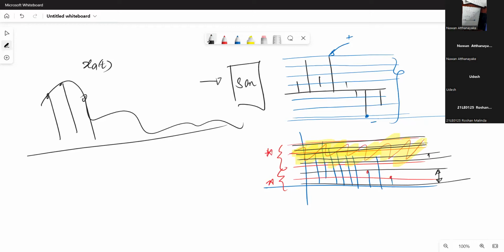They need 1024 levels to represent these, which means if you take the log base 2 of this value, each sample can be represented using 10 bits, because this is a binary coded one. That's why we took log to the base 2. If it is some other order, you can have log to the base n.